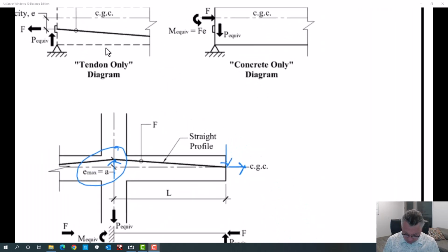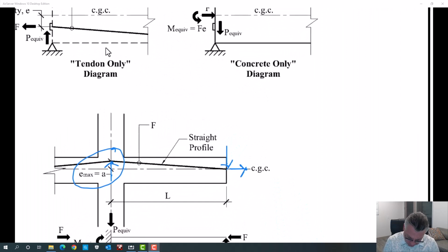You can also, and probably the best way, is to always just take the component of this, just like you did before, and that is the way to calculate that force. Calculate that one, and then that force, once you have it, times L, is the primary pre-stress moment diagram.